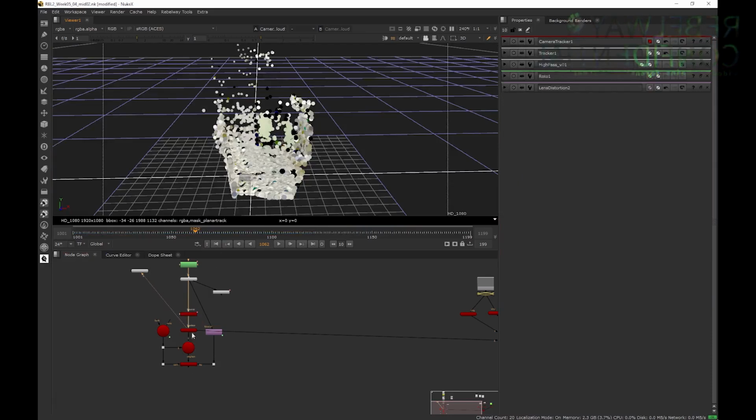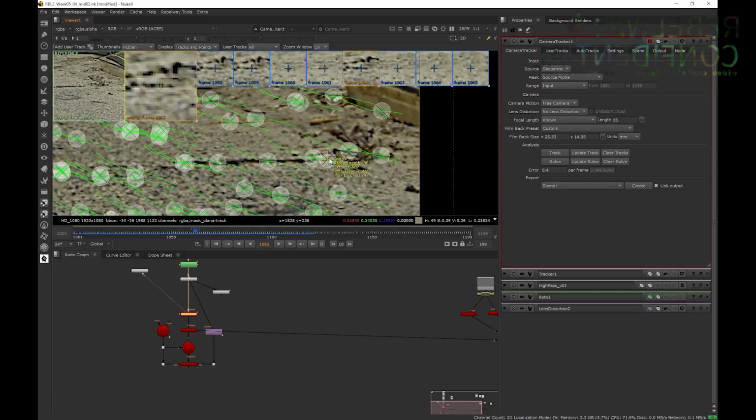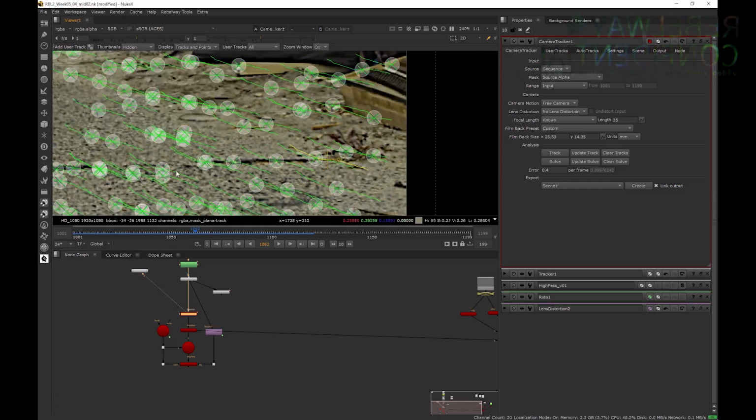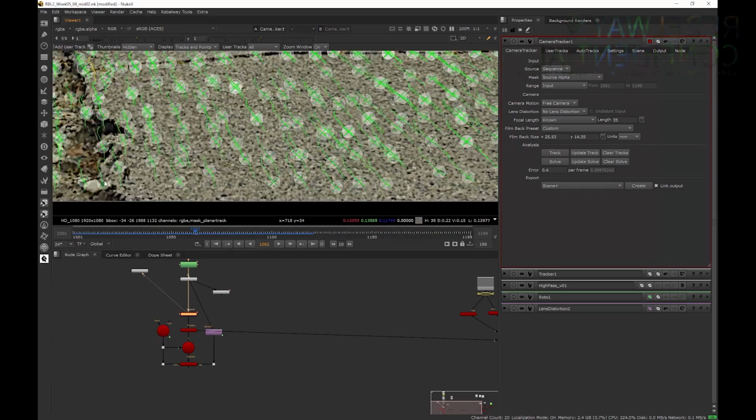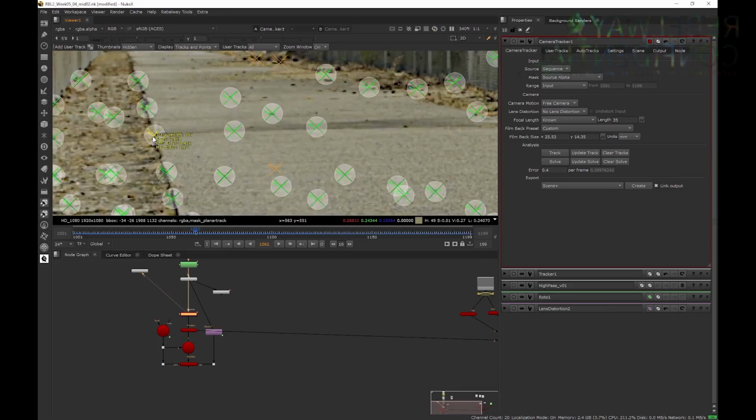What I want to do is use this point as our origin. So I'm going to go ground plane, set origin, and that should snap this to be right dead in our center. And then what we can continue to do, let's select our user 1 track. We'll grab this user 2 track all the way to the right, and we can set that to be our X so that that part is flat to the ground. And then right here, we'll grab our Z and just make sure that this is flat as well. We'll go ground plane, set Z.